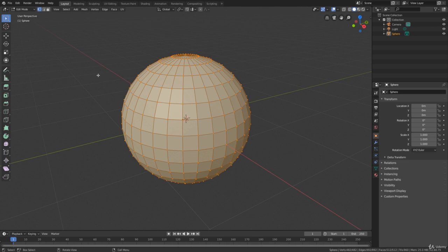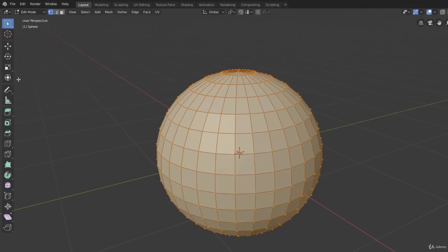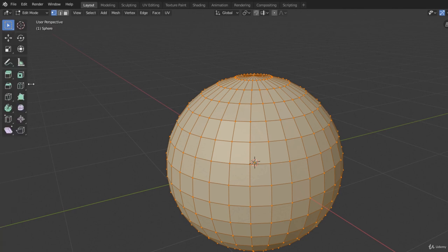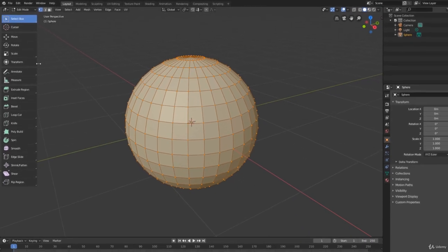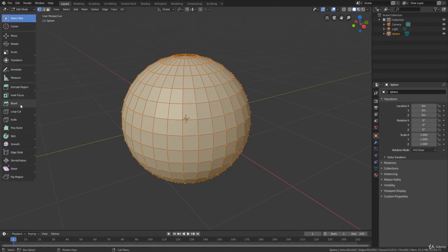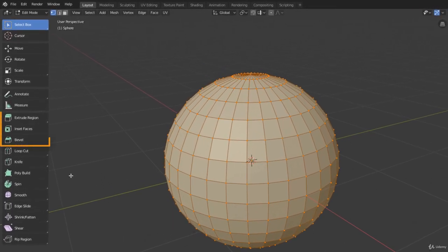I will click on the corner of the toolbar here on the right and drag to the center of the 3D view, so we can see the names of each button. The tools icons have a very good design, and when you know each of them, you can easily identify each tool by just looking at the icon. But while we are learning, it may be a good idea to make the names visible until we get used to the icons. In this lesson, we will focus on these first three buttons of the Toolbar's Polygonal Modeling Tools group: the Extrude, the Inset, and the Bevel.